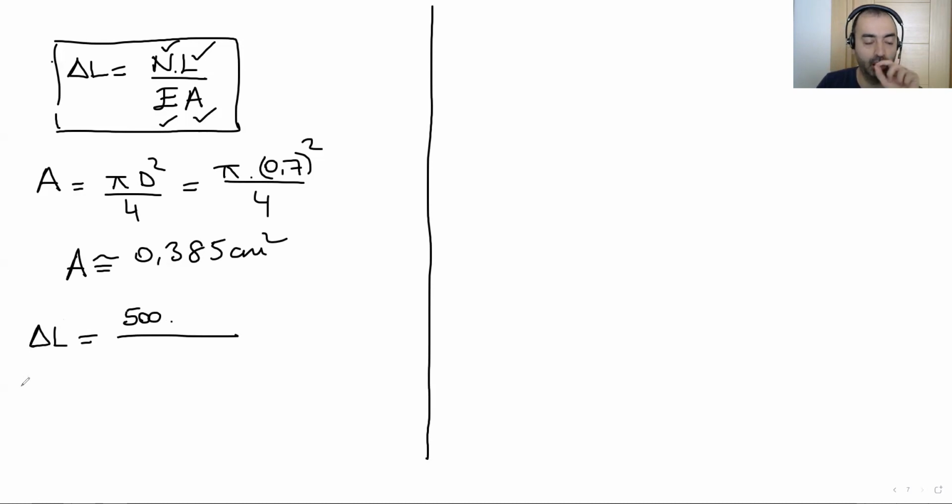By the way, in your calculations, you have to use the same units. Okay, this is kilogram. L is the length of the member, 9 meter. E, what was E? 2.1 times 10 power 6. This is in kilogram per centimeter square.